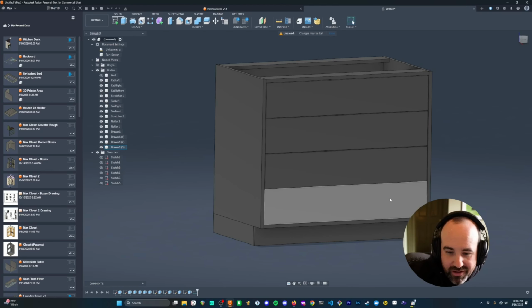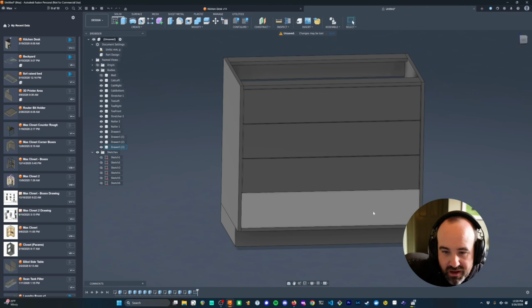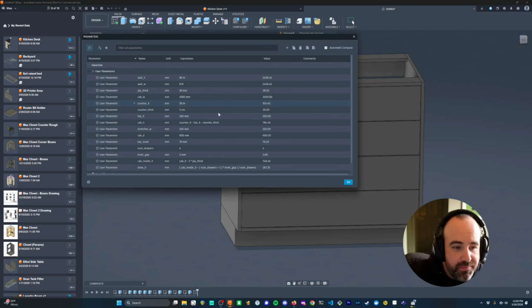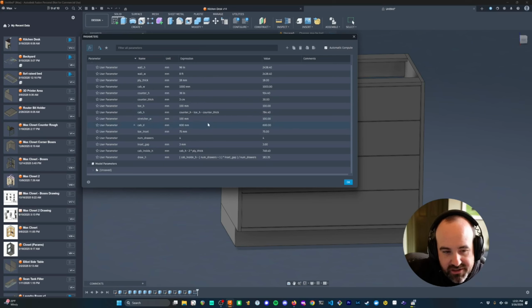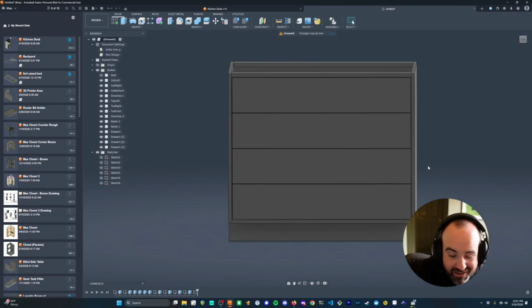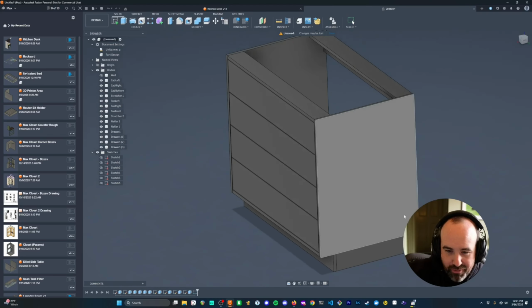And so I can go and put this in my cut list. I know exactly how tall to make each one of these. It's really, really nice. And that's the benefit of doing this parametric design. If I come in here and change some of the values, in theory, the design should update pretty easily. In practice, it usually doesn't work out that way without having invested time in making sure your constraints are set up right. As I was building this, I noticed a few places where I didn't have appropriate constraints.